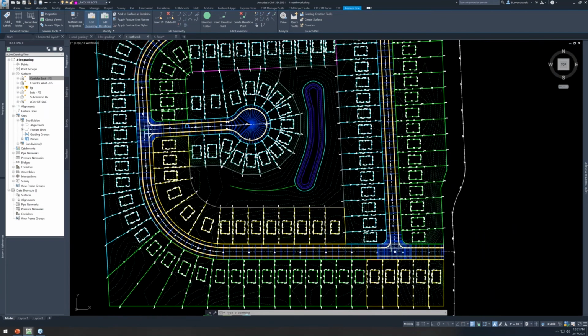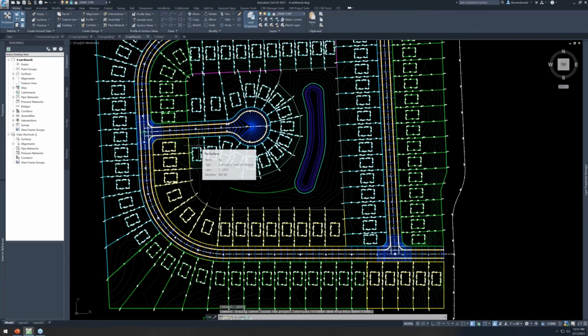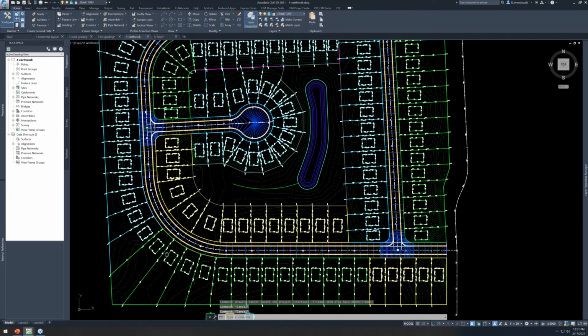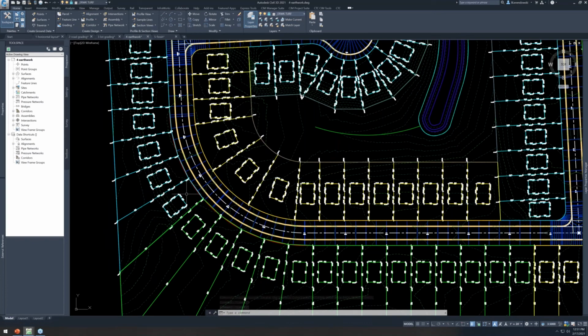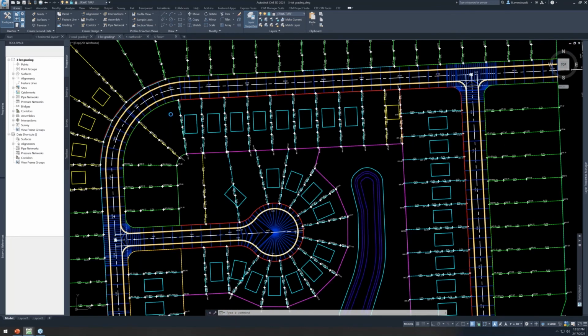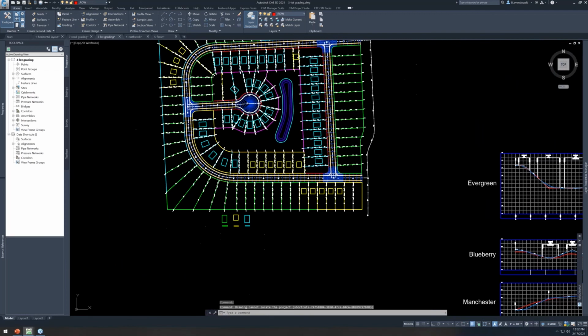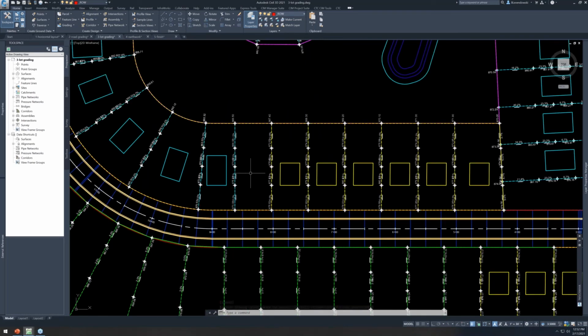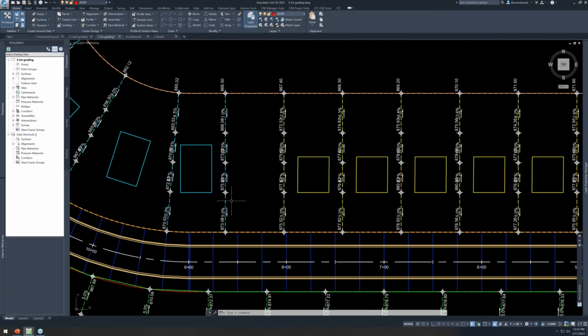Now let me move to Earthwork and kind of pull my baked cake out of the oven here. Again, to be able to get through this in an hour, I had to do some things ahead of time, but those processes I was just showing you, that's what we've carried out here. I'd also done a few other things. You might have noticed, like right here, well, where's the lot right there? Now we did this based on intersections, midpoints between intersections. So right here, it didn't find an intersection between two common lot line types, and nor does it know what to put there. So there you might make a decision, what kind of lot, what kind of house pad might I put there?